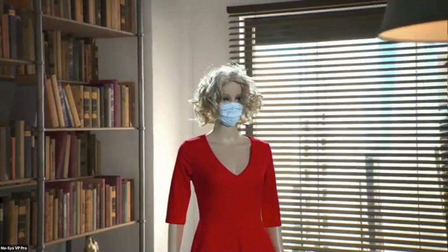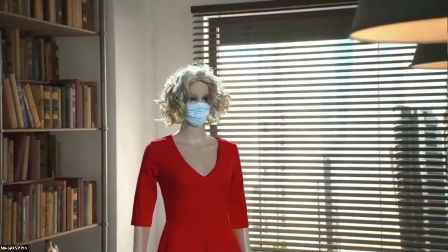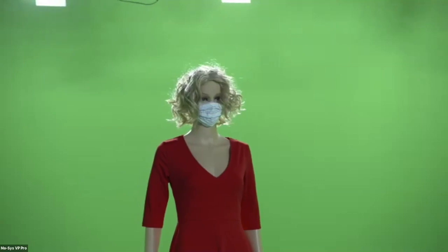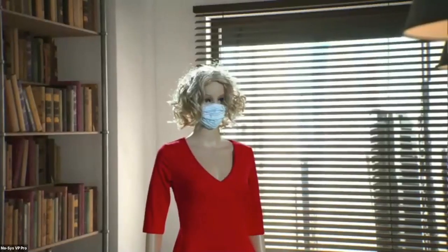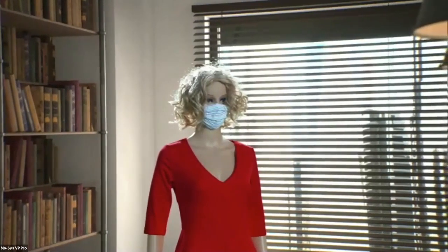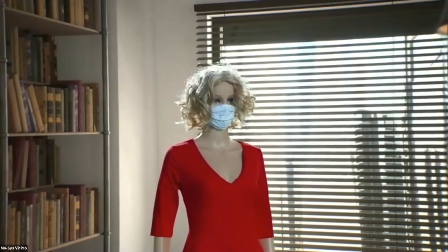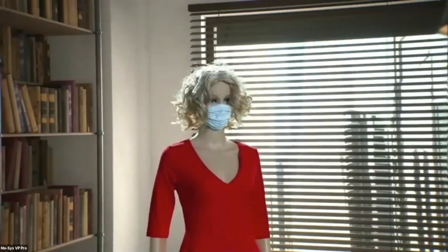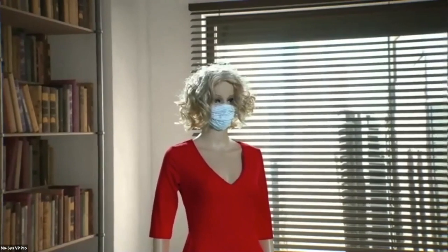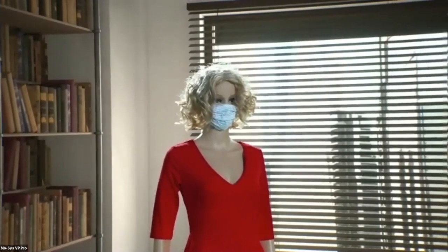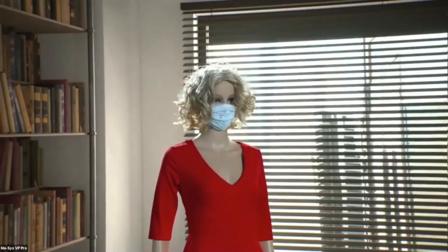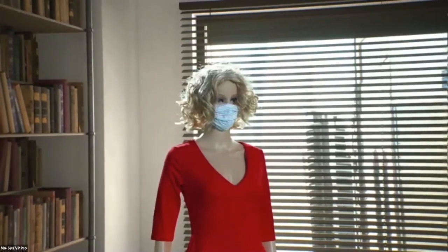So this is the keyer doing the compositing. You can see it's a very good quality key. I think I can show you, there we go. So that's what's coming from the engine. That is the matte, as it's called, that it's creating. And that's the final composite. So that's the Ultimatte creating that. It's doing a really good job of keying that. And of course, we can still move around because the engine is generating CG. And we're of course still handling the lens distortion because the CG has been distorted to match the real lens. Okay, I'm going to go back to sharing my screen now. We can leave that up.